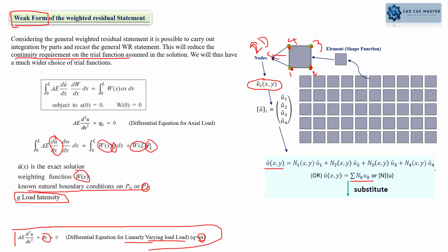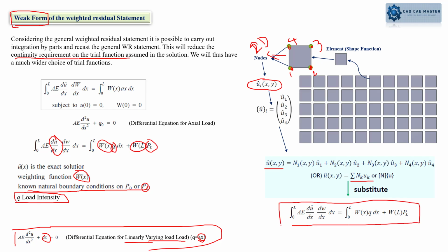With this we form the shape function by including the boundary conditions and weighting factor in the equation, where we take the weak form, and all these values will be substituted here. We substitute all of this, find the unknown values C1, C2, C3, and then directly put these into the stiffness matrix.